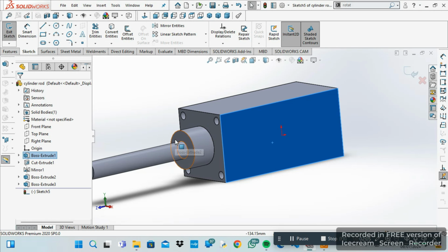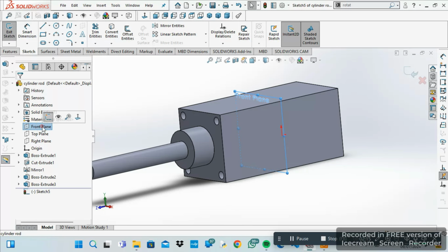A plane is a flat construction geometry. You can use planes for adding a 2D sketch or section view of a model, or a neutral plane in a draft or feature. These are the three planes: front plane, top plane, and right plane. You can also add extra planes called neutral planes to your sketch or your drawing to add further dimensions to your components.